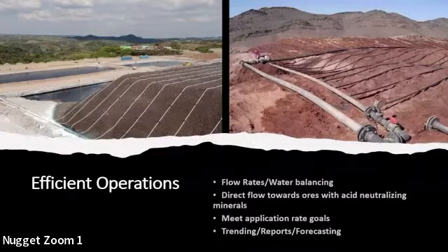Now, when you are in the white range of that graph, that's above the 100x safety factor. The hydraulic conductivity is above 100 times the target irrigation rate. When you get into the yellow box, you're now below that 100x factor. You're above the target irrigation rate of 0.003 GPM per square foot, but you're below the 100x safety factor. And when you're within the red box, at that point you are below the forecasting irrigation rate.